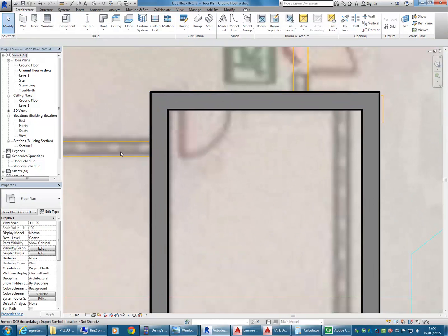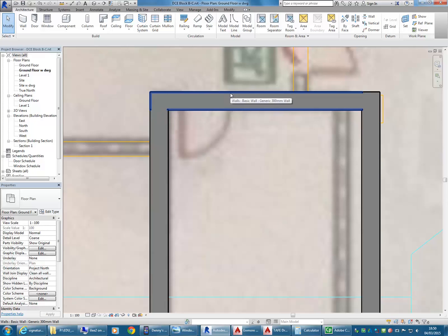where I've gone over those walls, I can't see the plan drawing anymore. So one little thing I just wanted to show you is in these views, well, you probably know that you can set wireframe as the graphics option to see through some things, and when we do a floor that'll definitely help, but having set it to wireframe, the walls still aren't see-through.